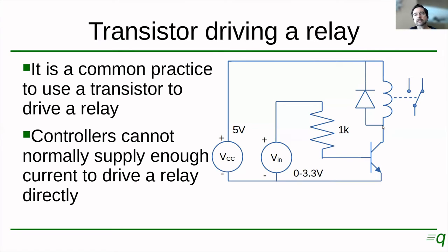And that's going to limit the voltage here to 0.7 volts above the 5 volts that we have on the supply. If we didn't have this, the collector voltage can shoot up maybe to 100 volts or so, and that may be damaging the transistor.